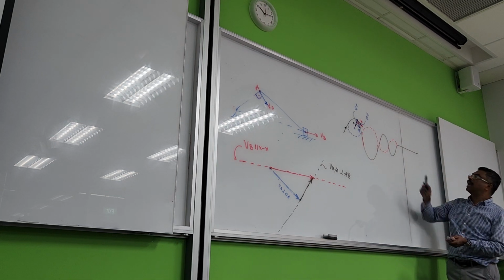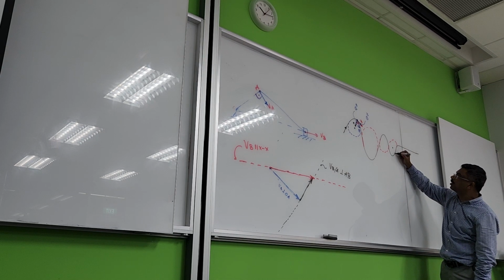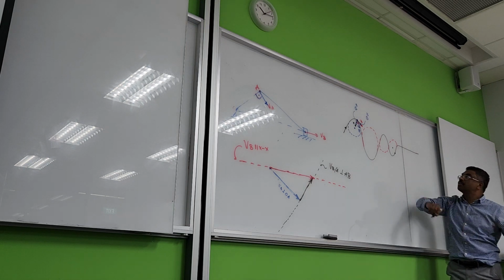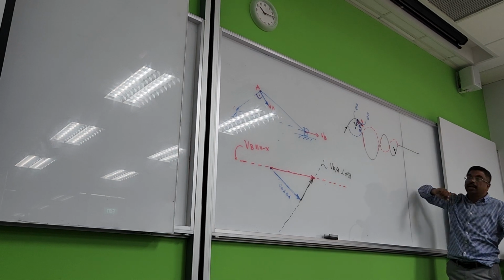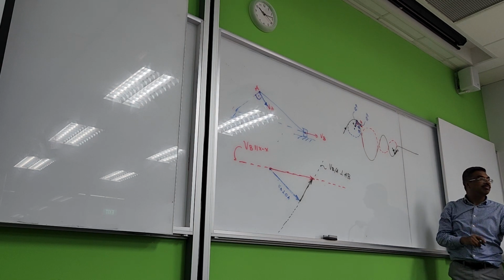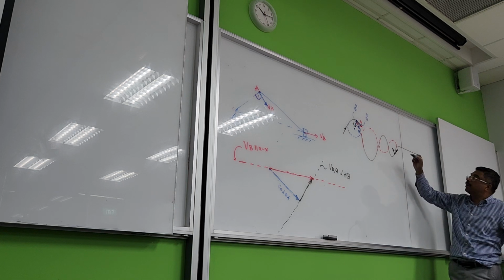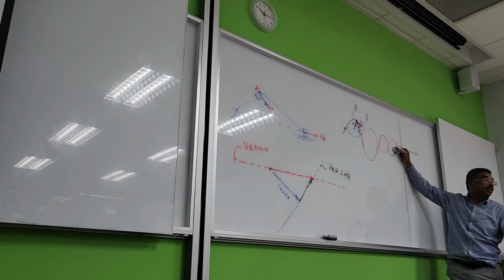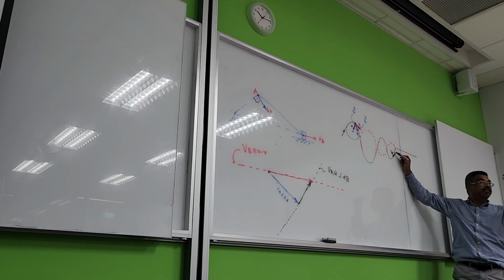So now look at here. Let's see when our particle is here. This is our center, and our particle location is here. So from here toward the center will be our n coordinate system, and perpendicular to it is our t. You see, I follow the grammar. I don't follow anything else. I first look at where our position is, where the center of the circle is. From the position to the center of the circle will be the n coordinate system. I will always draw n first. I will never draw t first. If you draw it first, that is the wrong thing.